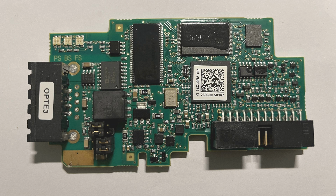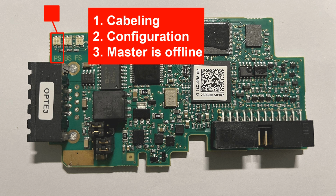Meaning of the status LEDs are as follows. PS LED is red and it is used to indicate Profibus status. If it is off, it means that Profibus DP communicates normally. If the LED lights, then it means that the Profibus DP connection is broken due to a broken or incorrectly connected field bus cable, wrong configuration or parameterization data of the master, or the master is offline due to power loss or faulty interface.